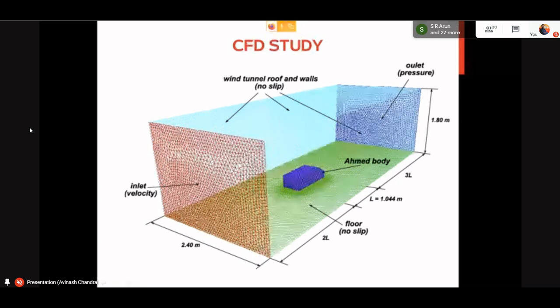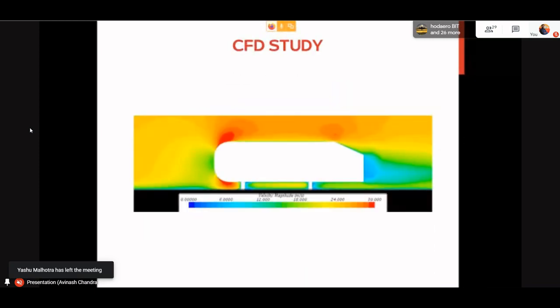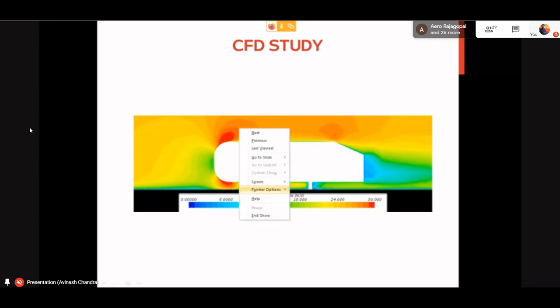If you want to find the velocity over here, from here, the value of velocity from this point to this point, you have to somehow correlate. You cannot just measure it. So what the meshing does is split the volume into millions of parts. So one small part from here to here will correlate with the next. Like one element is here, then behind there will be one element, then again. So there will be a chain of elements connecting to each other, filling this whole volume.